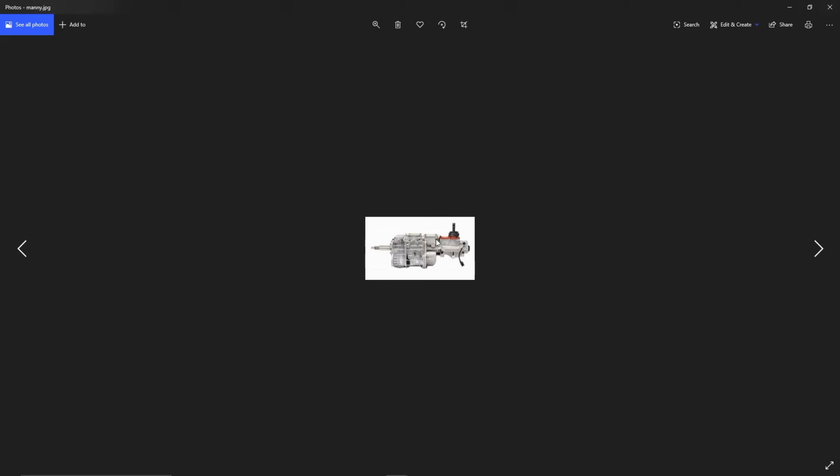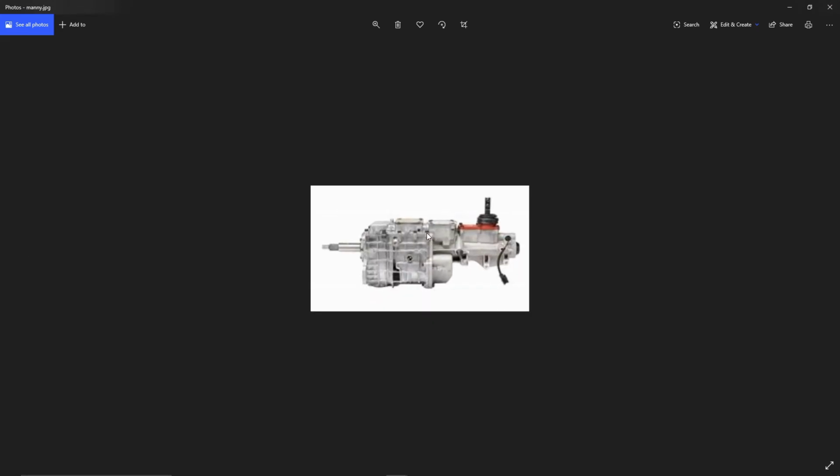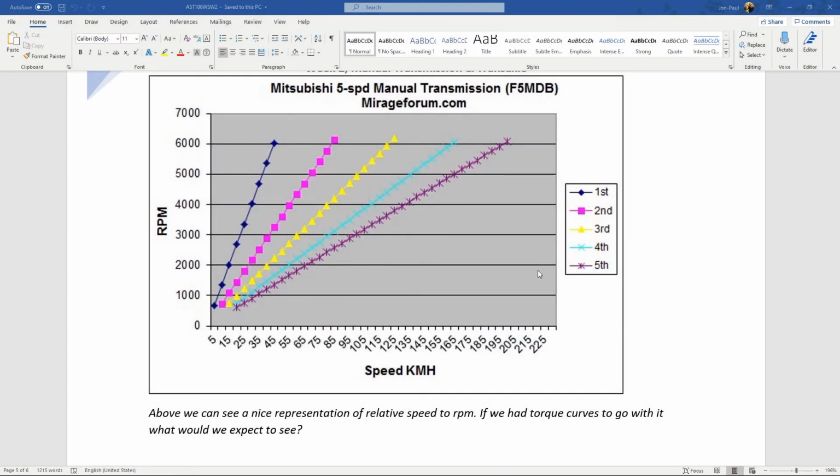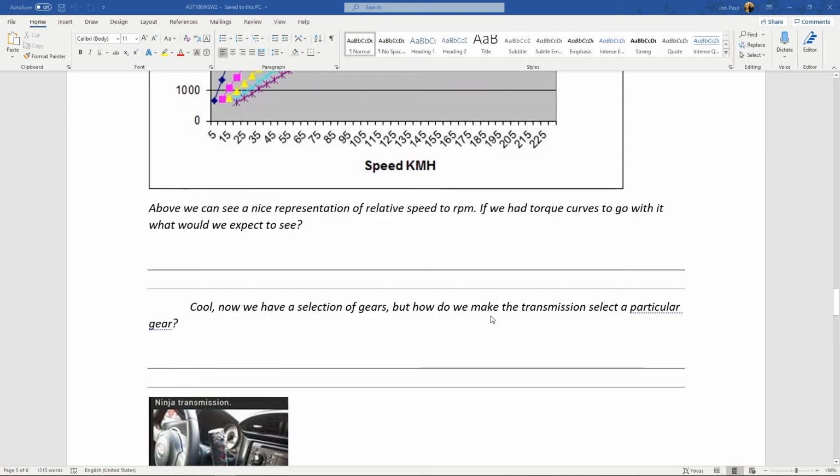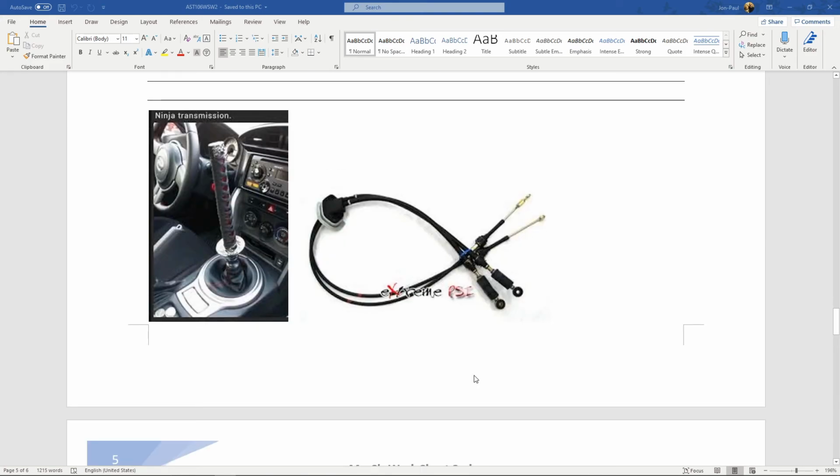So, oh, it's little. Blow that guy up. So, you went off-road mudding in the Cherokee, and you submerged the transmission in water, and water got into the vent on top, and now the transmission is full of water. Water is not a great lubricant, and it will absolutely wear the transmission out. Differentials work the same way. They also have a vent on top, so just be mindful. If you go out playing, you need to check the fluid when you're done.